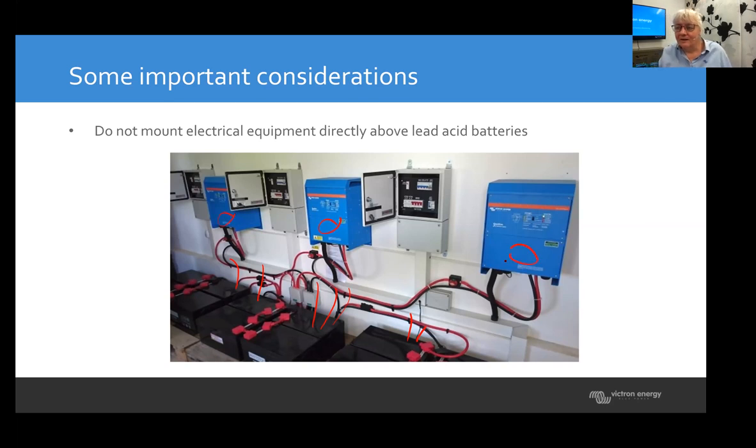They can make a spark and then kaboom, things blow up. Or all the electronics get corroded in here. It's not good. So they need to be on the other side of the wall. Or sometimes you can put a shelf in between to physically stop fumes going above. So a shelf would have done the trick there, or something like that.